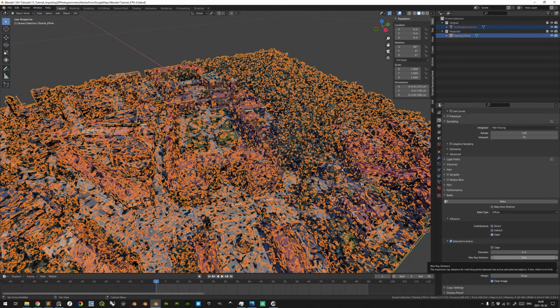Right, when defining the maximum ray distance, one has to take into account the dimensions of the imported mesh. These are not in any way one-to-one with real-world scale, so one has to consider this, and it is rotated around the x-axis as well. So the Z dimension here is not the world Z, but actually this longer horizontal axis. It's about 87 by 47 centimeters.